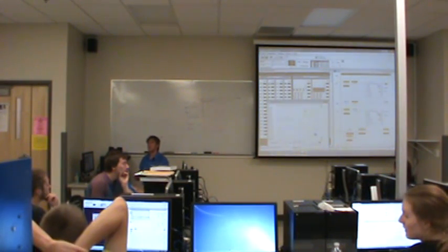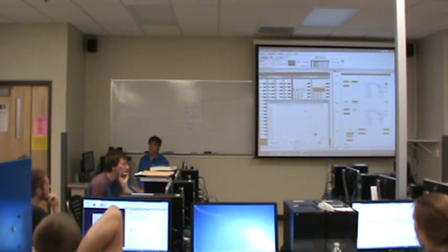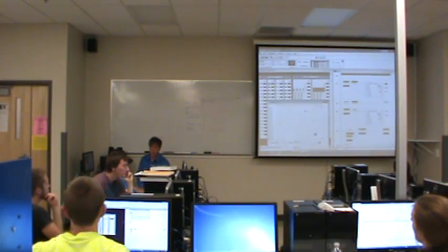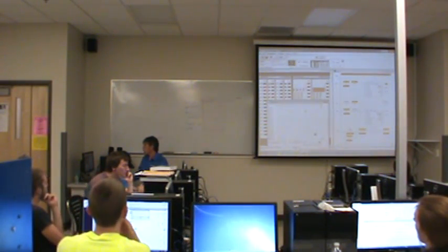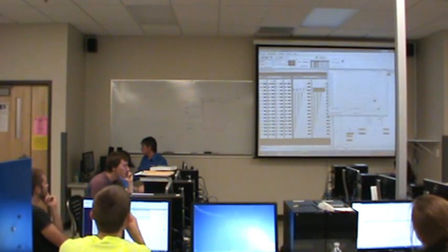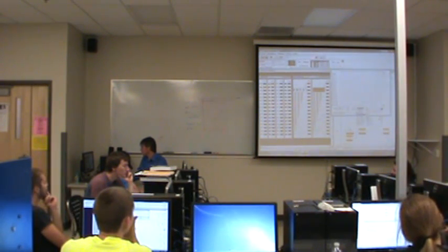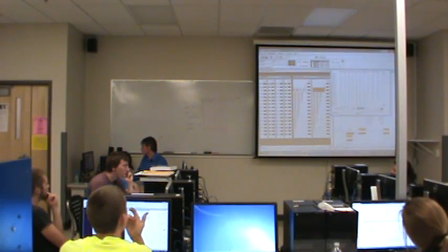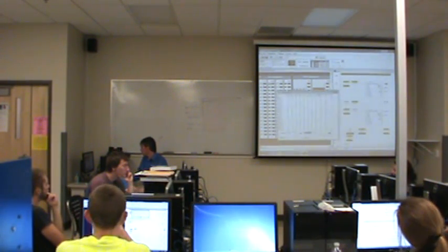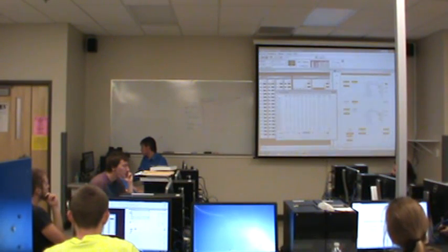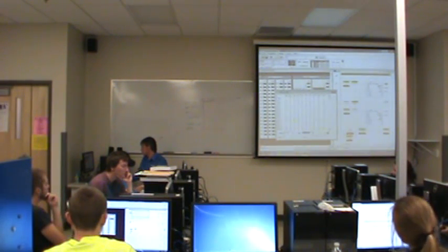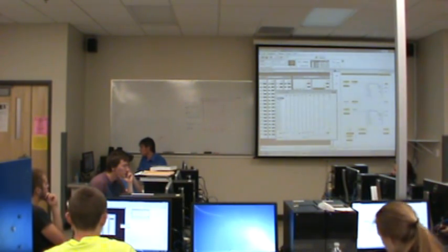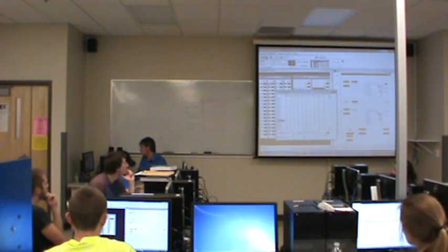Yes, sir. Could we go backwards? No, you cannot make it go backwards without writing to the memory address directly. You can make it go backwards, but you have to be really tricky. It turns out that you can, if you go to the registers file, and you know what you're doing, I'm not sure that I would. The control registers are at 0 for the sequence compare, and at 10, that's just where I happen to assign them. So 0 for the compare, 10 for the output.